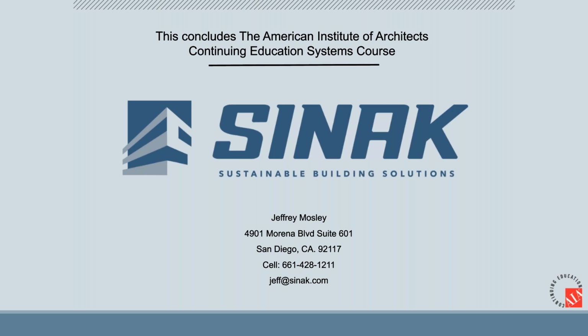So I usually specify a vapor control system where it's necessary for flooring, and an exterior and an interior. Breaking out by application is really important to give your contractor the right guidance to eliminate the risk. So for me, to reiterate, I always pour on the plastic. I always cure with a water curing equivalent product, and I always ensure I control the rate of drying. Those 3 steps ensure that when my flooring does come in, it can be installed properly without risk of failure.